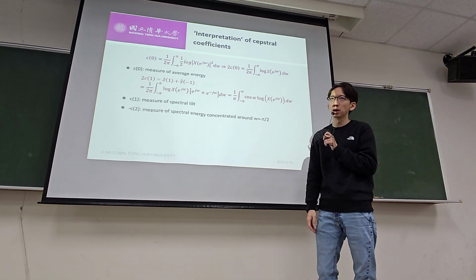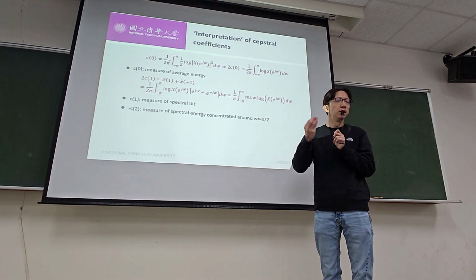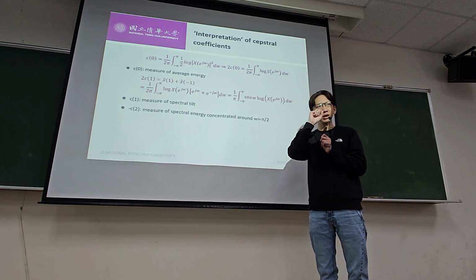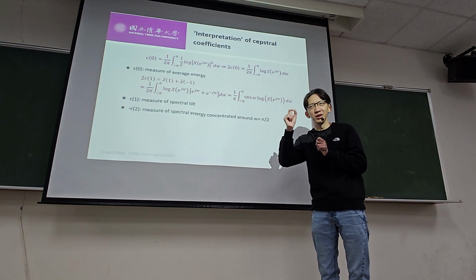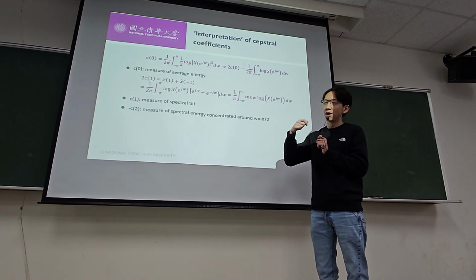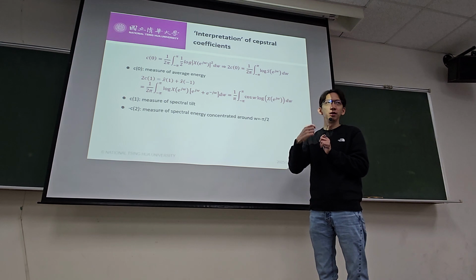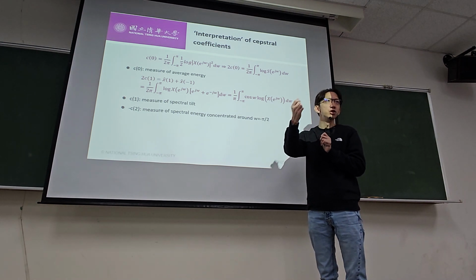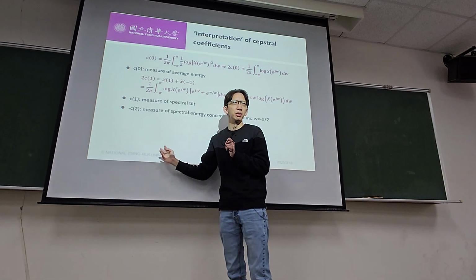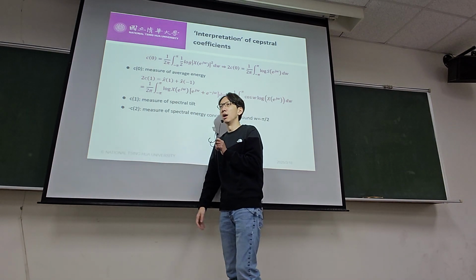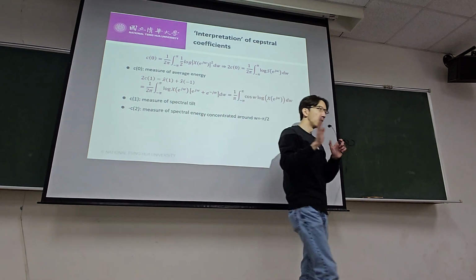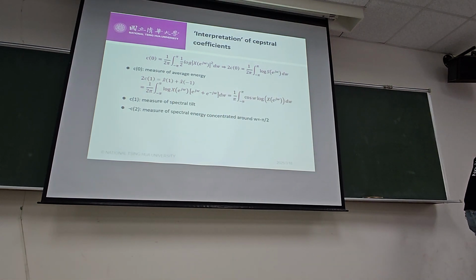But I feel like for the cepstral coefficients, the actual physical meaning starts to become quite loose. It's very difficult to really know what each coefficient means. You can imagine this is basically a reparametrization, a recharacterization of the original spectrum. You don't really have an idea of what each coefficient means anymore. You lose that physical interpretation, except for the first coefficient, which usually means the overall energy of the signal.